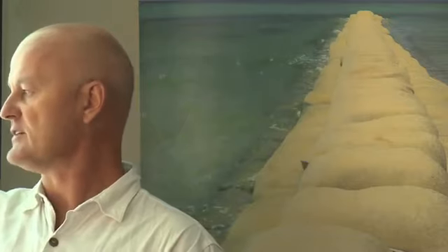It also increases for steeper revetment slopes. So as we go steeper, we can withstand bigger waves, which is a little bit counterintuitive. If you're used to designing rock structures, that's not necessarily right, but because of the interlocking and the way that gravity acts on them, they lock together more as you go steeper, but that introduces other problems.